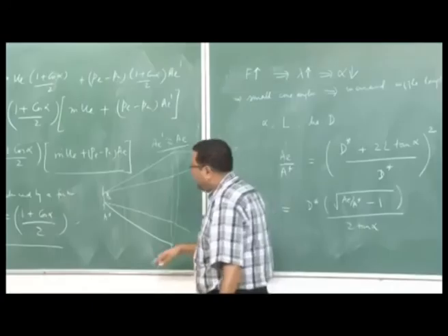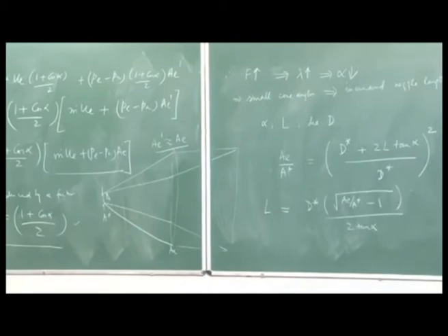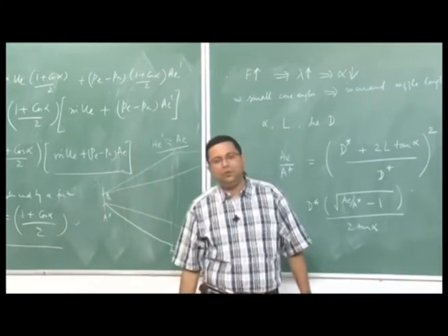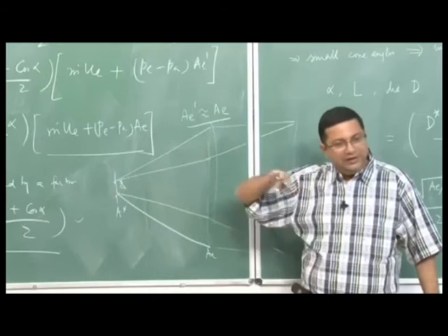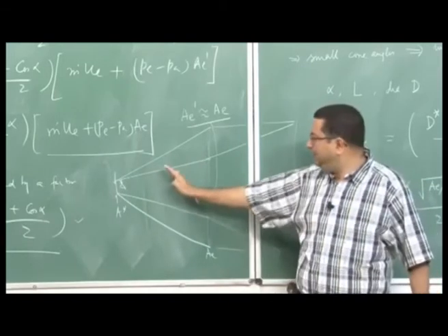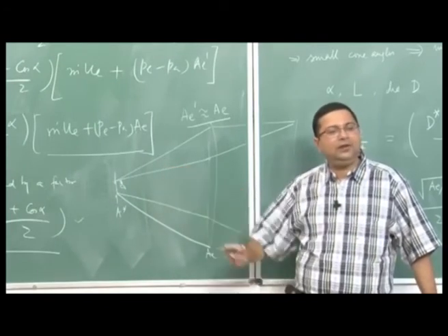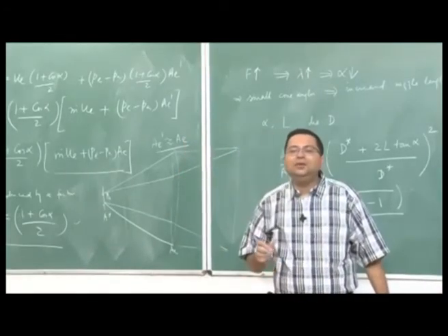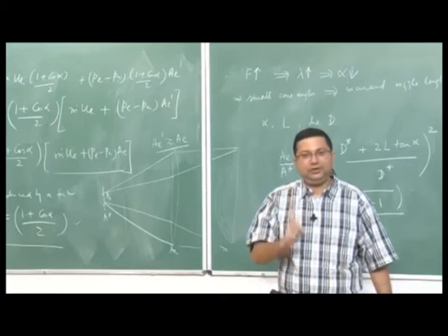So, we have to then look at some other alternative to address this issue. So, one of the ways then will be, instead of giving a fixed angle, what if we vary this nozzle angle over the length? Here, if I look at it, there is a fixed divergence, so acceleration is almost constant everywhere. Instead of that, what if we give a smooth variation in such a way that we can get our flow to turn the way we want to? That is the first advantage.